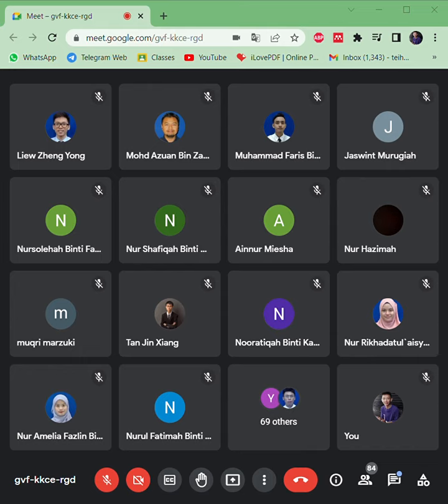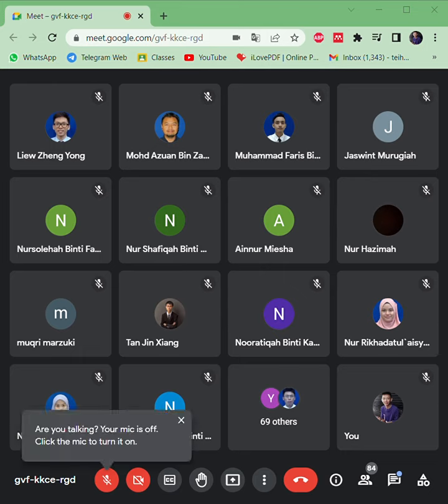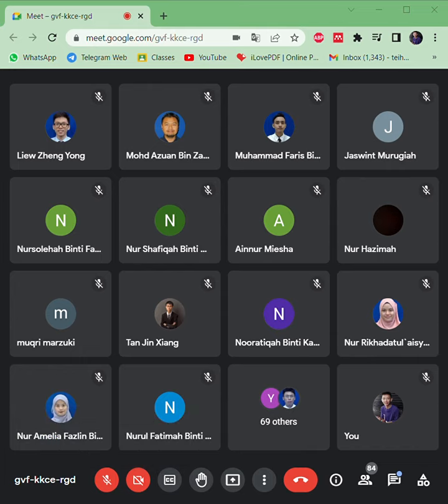For the U value, normally we need to calculate one by one. So the U value of glass needs to be calculated, and the U value of the brick wall needs to be calculated if it has several layers. So then we have two types of U value. To calculate the overall or average U value, we need to use this equation, right?